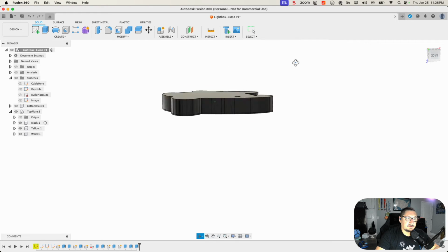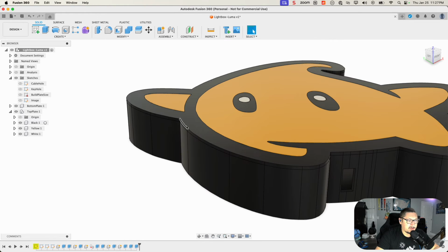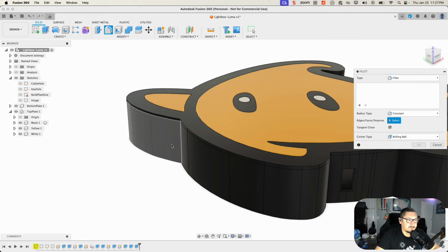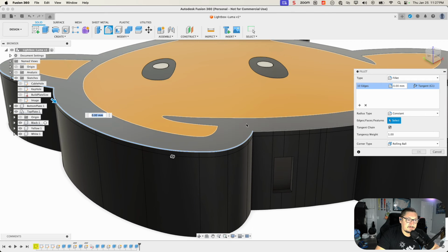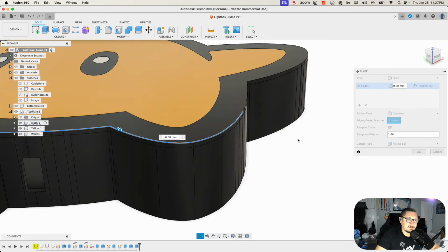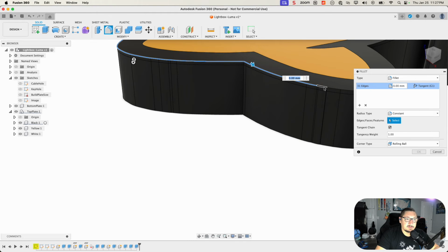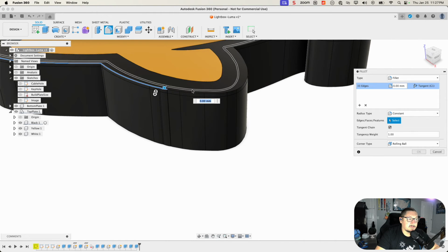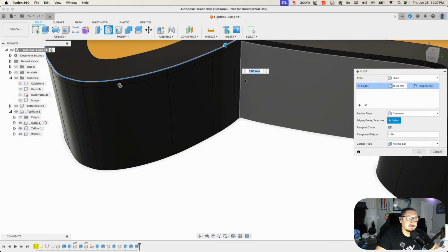And then if we come back here or go back to our home, one of the nice things that I like to do on certain things, if the geometry plays nice to it, is instead of having this rough, solid outline, what I'll sometimes do is put a fillet on it. So if I can daisy chain these up a bit, and sometimes it lets you, sometimes it doesn't, depending on the tangency of the curves, we can go ahead and select, and we probably can. It's probably easier if I just do this in not a gigantic operation, but we'll give it a shot.